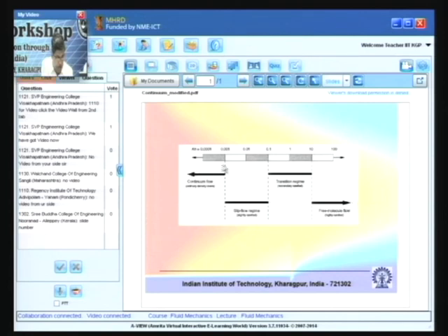This is the criterion of the Knudsen number. For all our ordinary fluid mechanics studies, except flow of gases at extremely rarefied pressure, where the Knudsen number becomes high in the range 0.1 to 10 or even more than 10, or fluid mechanics through micro devices, as Professor Suman Chakraborty explained, nowadays with the development of MEMS, micro electromechanical systems, the continuum approach is valid for all other cases of fluid mechanics. Okay, thank you.